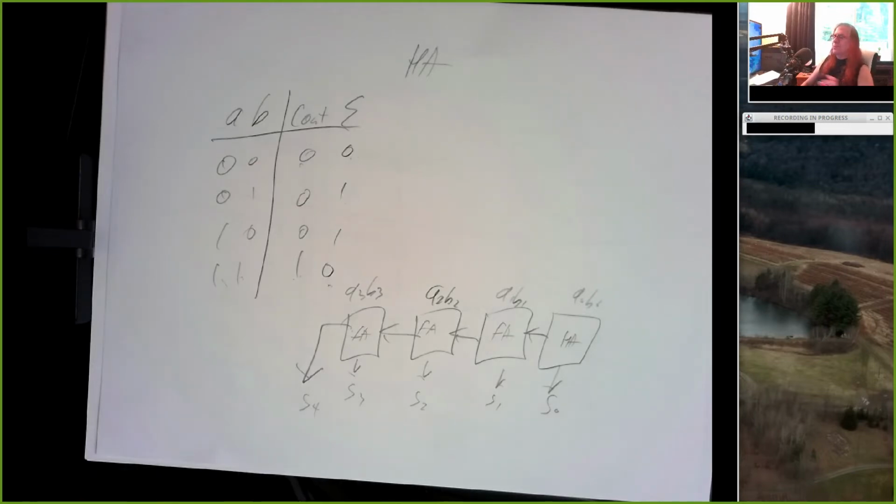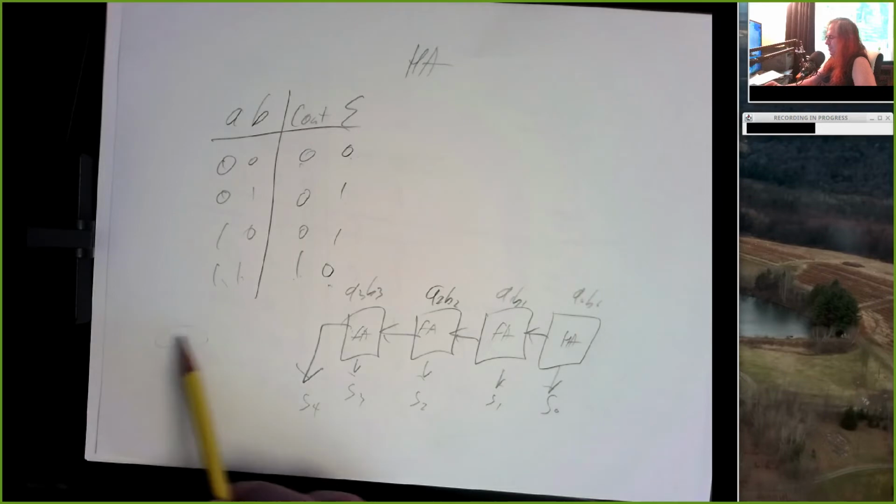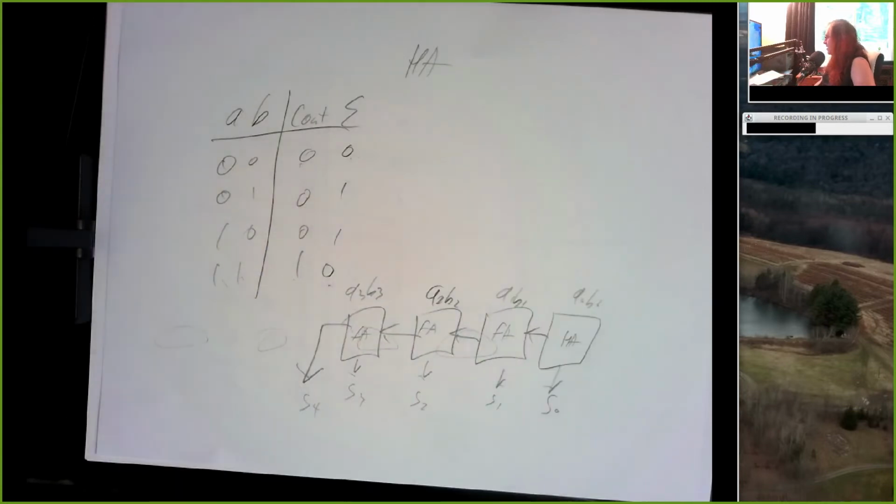And it's not a horrifying circuit, but it does take a little bit of planning. So you know, maybe put your chips down on the proto board first. You do your schematic first. You get your component ID block. You know how many of each gate you need, which tells you how many of each chip you need. And so first thing I would do is probably get a big proto board and lay out your chips. They have to go across that middle section, one on each side.